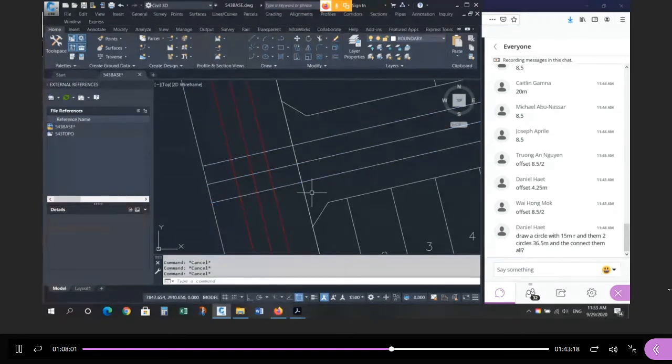Okay. Now again, that term pavement is confusing. This is an urban road. And when I say edge of pavement, I mean line to gutter line. If you remember, this road here has a shoulder. So this is a rural road. It's not an urban road. There's no curb and gutter on this road. So now how do I connect this gutter line to this road here where there's no gutter? Okay, and this is the trick. Connect this to where the gutter should be on this road.